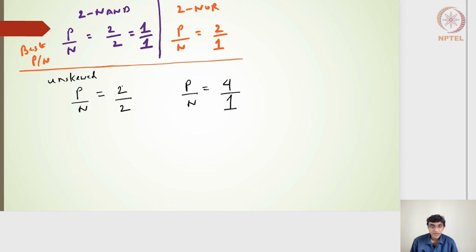The size of 2 is required on the NMOS side to get to the falling resistance of the benchmark inverter, and the size of 2 on the PMOS side is there for the 2-input NAND gate, because either of the branches will be on, and then I'll have the rising resistance equal to that of the 2:1 benchmark inverters. So once I have this unskewed form, which is considered from making the equal rise time or the equal falling time,